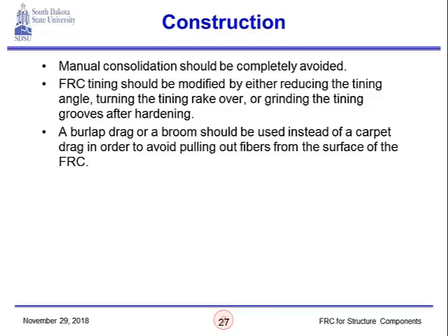FRC tining should be modified by either reducing the tining angle, turning the tining rake over, or grinding the tining grooves after hardening. These are recommendations based on some of the interviews that we did with some DOTs that had previous experience with FRC, and they had this issue where, when they do tining, they pull some of the fibers off the surface of the concrete. And so these methods could be used to avoid pulling these fibers from the surface of the concrete.